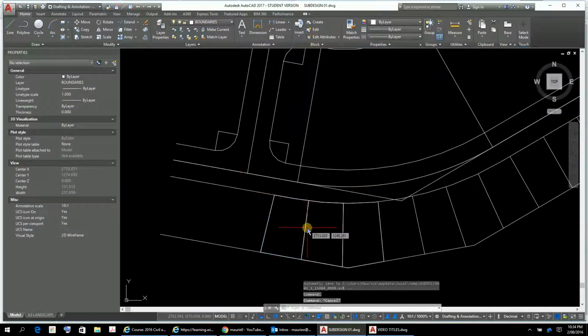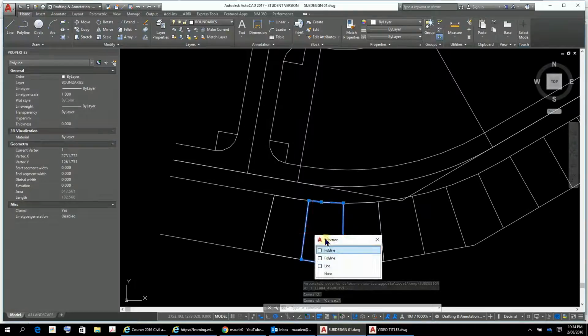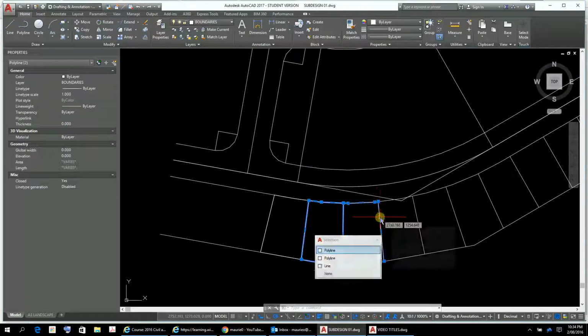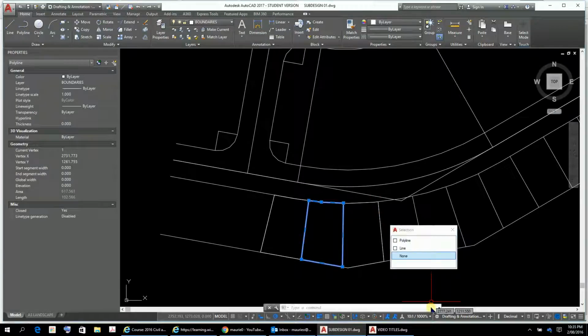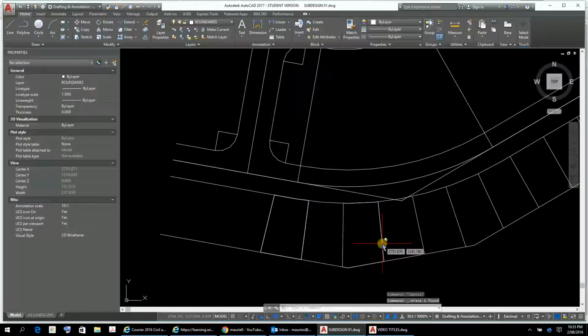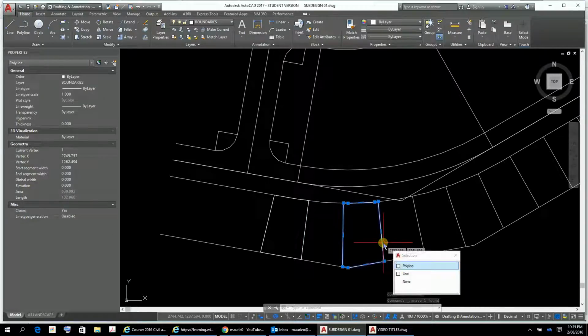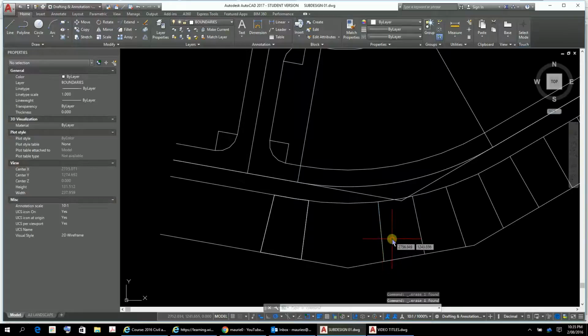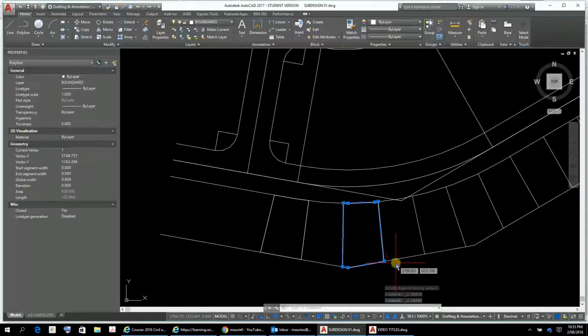So because that's now straight and not curved, we'll get rid of these, delete, I'll delete that one. I'll just extend this little video to finish this side, I think. Polyline, delete, so we're at 12 minutes now, and possibly take it out to, oops, RE to regenerate. Oh, Control Z, okay. So I might have taken a line out there. So there's the polyline. We'll just delete that.